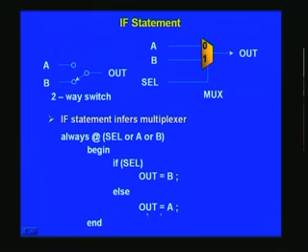and out will be assigned A now. And notice that we have fully covered all the possibilities here. The only possibility is select, so you have only 2 states. So we have covered it completely here, and that's how it is basically a mux, which is precisely the same here. That's what we said, that an if statement normally infers a multiplexer as such.